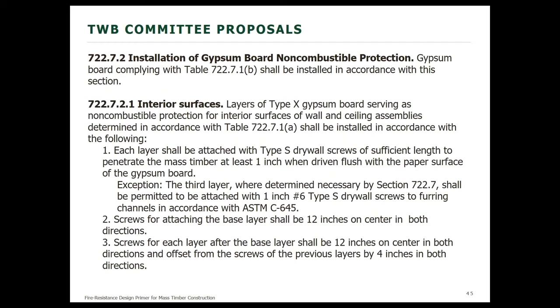These are a couple more of the detailed provisions associated with the installation of the gypsum board non-combustible protection. Basically it provides the prescriptive nailing or screwing patterns that are necessary to keep the layers of wallboard in place.